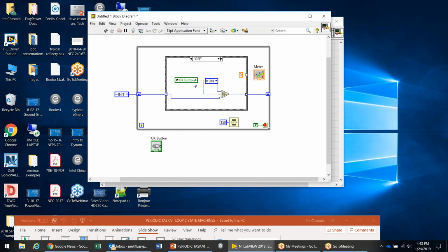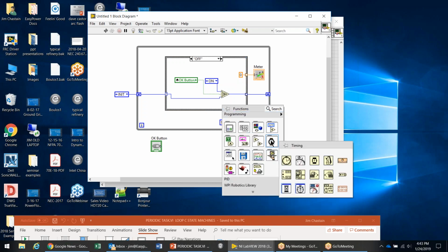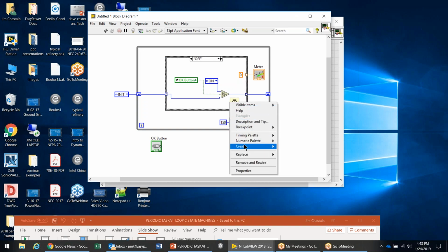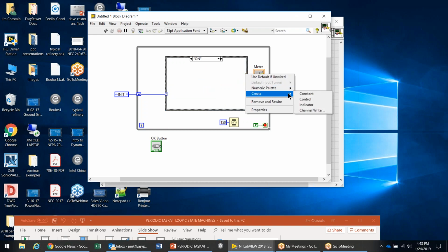Now, one of the things that I like to do, a drawback in this is that if you hold down the button too long, you can cycle all the way through multiple rounds of this. So I like to put a little bit of a delay inside the loop. And so if we've got 150 milliseconds as far as the total delay, I'm going to put about 50 milliseconds here just to kind of give it time so we can let go of the button. All right, so we're going to go to the on state. Now again, our motor will be at the control or the run value, which will be 0.5.